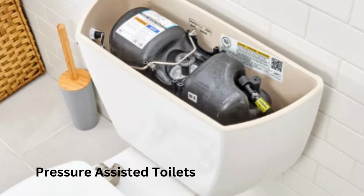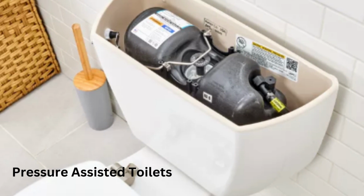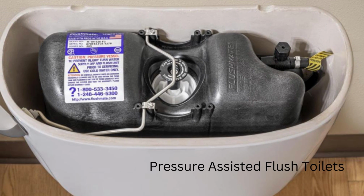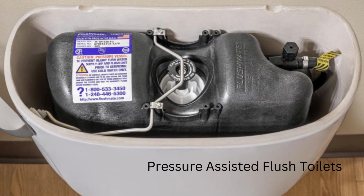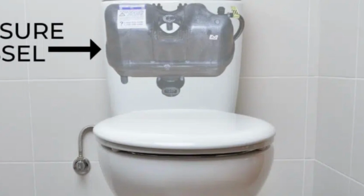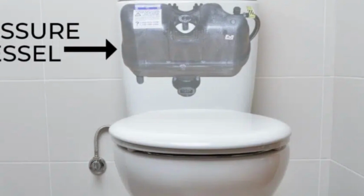The basic design of a pressure-assisted toilet includes a water tank that is equipped with a sealed inner chamber. When the toilet is flushed, water from the tank is forced into the inner chamber, which compresses the air inside. This creates a high-pressure burst of air and water that is released into the bowl, which helps to clear waste and prevent clogs.